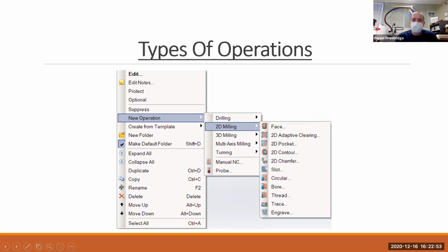Reaching into the operations that we generally run for, let's say, this piece right here. Whenever we cut it, the first thing that we did is set everything up and made sure it was oriented in the right place. And we were cutting off of either the top or the bottom. And then we didn't need to do a facing pass like we did with the other one, but doing a bore and clearing out this material and doing a 2D contour and going around the outside is all we needed. So it made it real easy to go through those two.